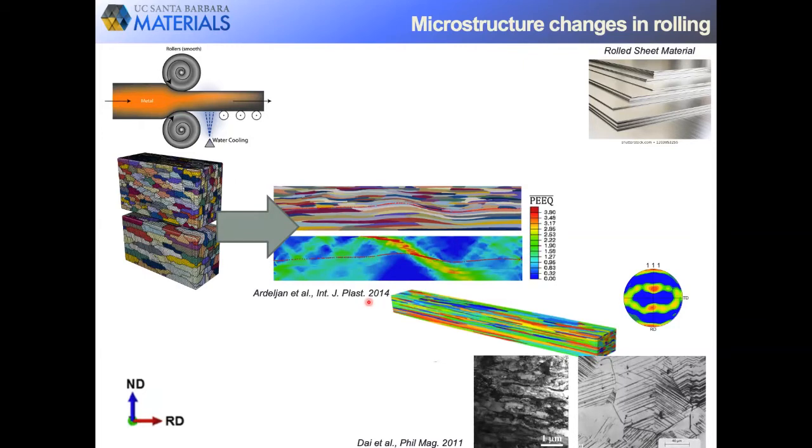And while individual dislocations are on the atomic size, thousands of dislocations are responsible, as you can see, for the displacement of just one of these grains. And in fact, in just one of these slip traces and just one grain, thousands of dislocations in their glide action are responsible for this deformation. So when we think about severe plastic strains, such as those that are incurred in rolling, we need not account for every single dislocation, but we think of their action collectively as slip.